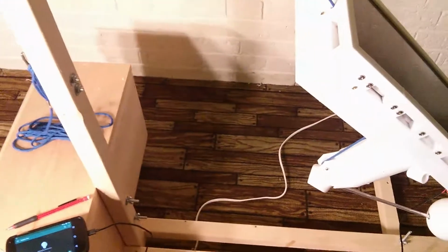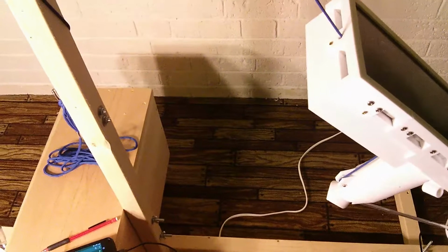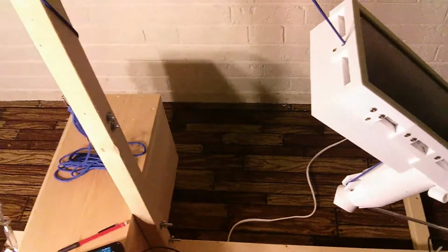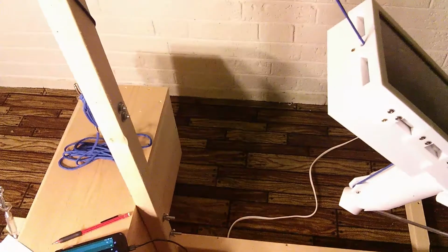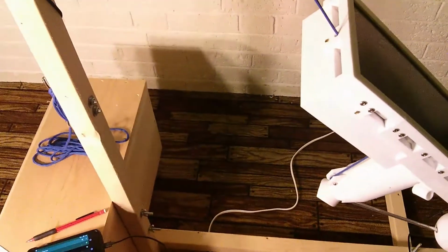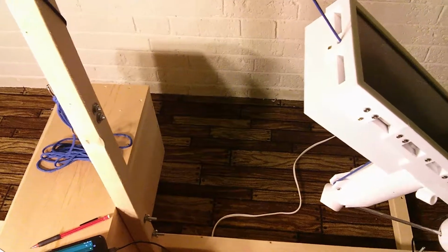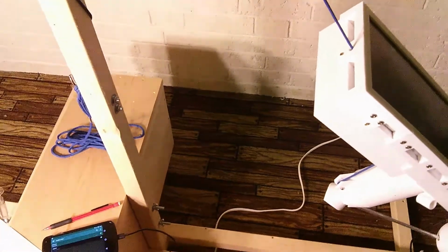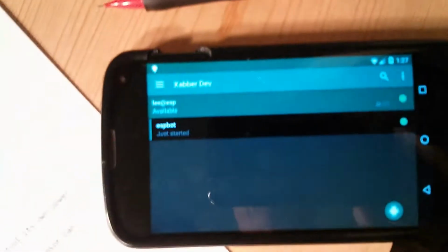And when I plug this in, I'm going to show you what happens to the spotlight up here. Okay, it came on, then it went off. The reason it does that is because by default the craft keeps the light on when it receives power, unless the Pi or the ESP turn the light off. This allows a fallback to occur where if those things go down, the ATtiny can get control over the light. And so I'm going to go ahead and show you now what happened.